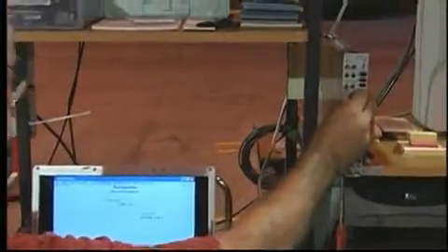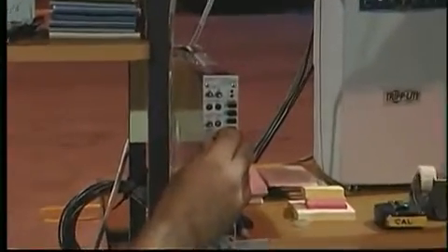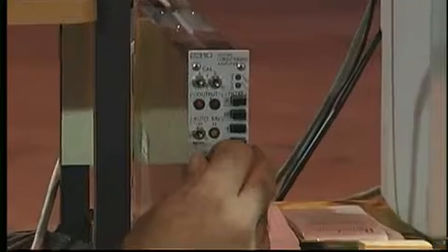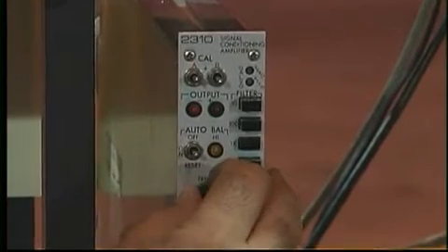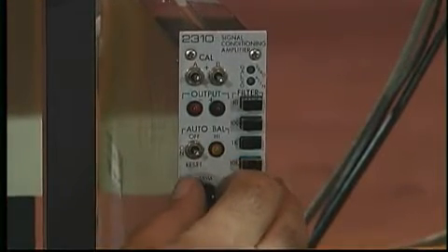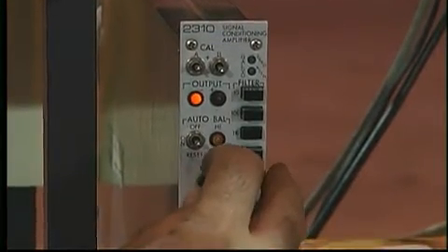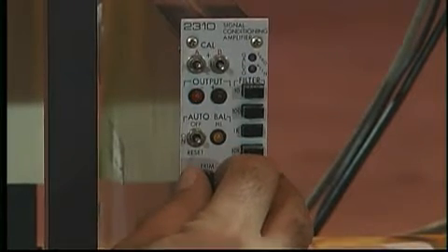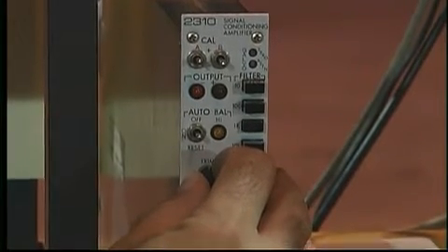Before load cell calibration, the center operator adjusts the settings on the front of the signal conditioner. As with deflection sensor reference calibration, a series of drops are completed to calibrate the FWD load cell versus the reference device. The reference load cell is accurate enough that only a reference calibration step is needed.